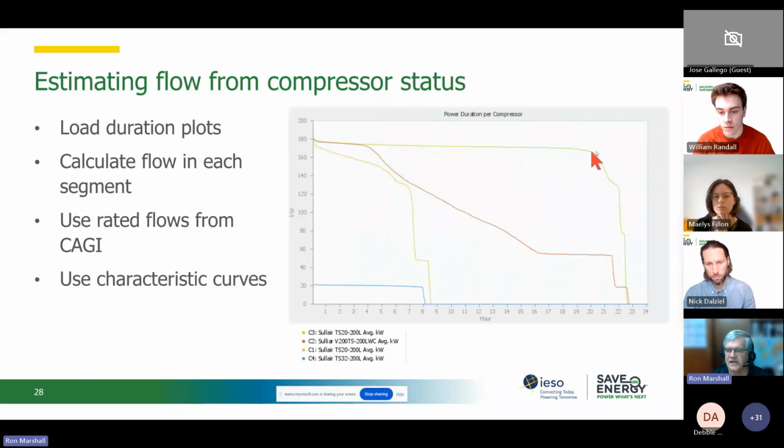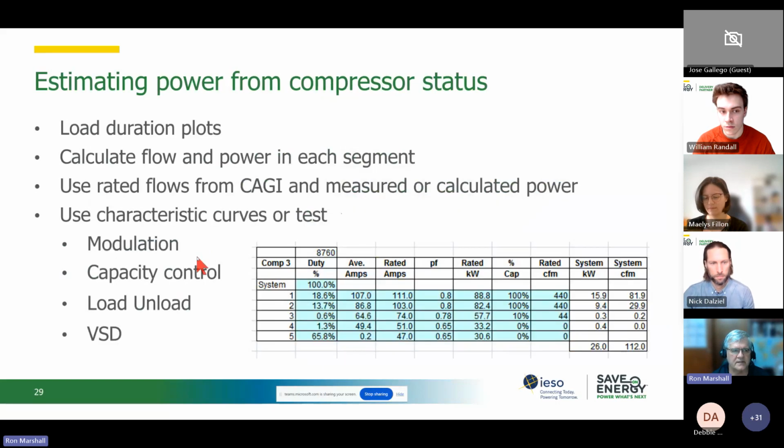These two compressors are actually positive displacement compressors, so there's some modulation with positive displacement, and here's unloaded, unloaded. And what's this? This compressor is running unloaded, not doing anything, right, through a long period of time. So that tells me that there's something that could be done about perhaps through control, and we'll get into an example in the later slides, right?